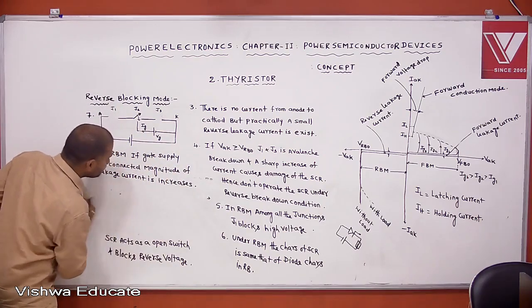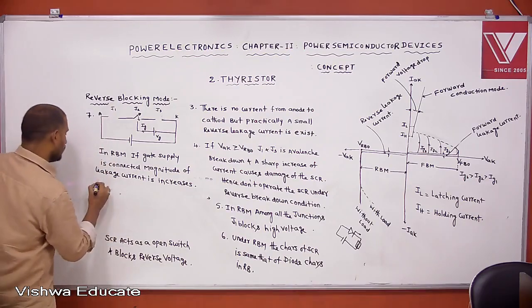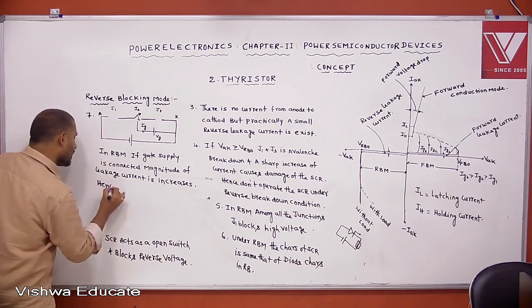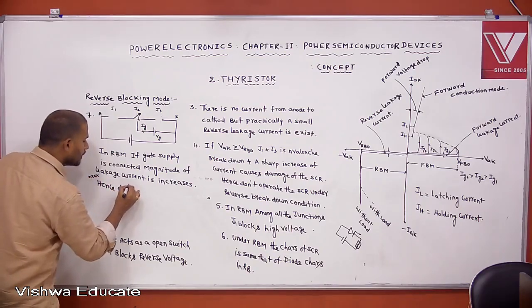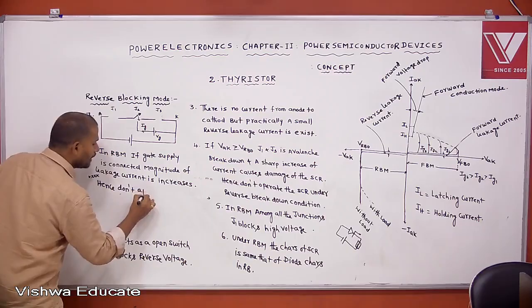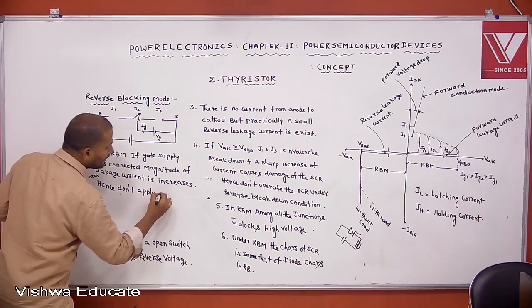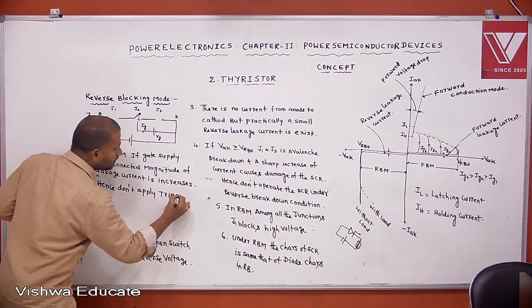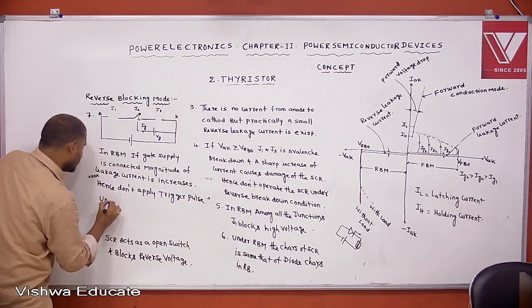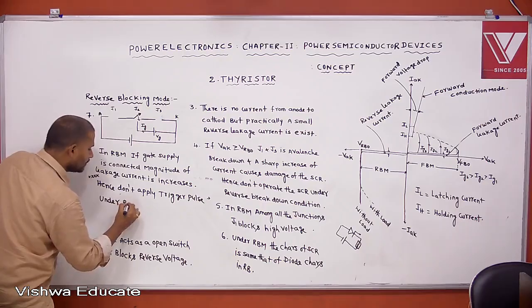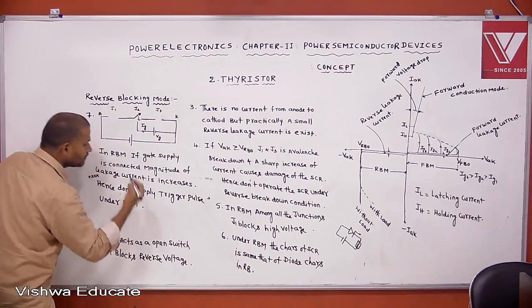Hence, don't give the triggering pulse. Very important point. Don't apply the triggering pulse under reverse bias condition, under reverse blocking mode.